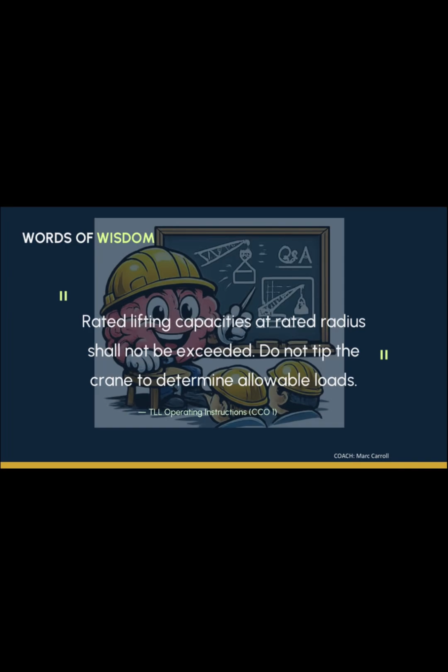Dynamic swinging. Control your load. The rated capacity is strictly based on the freely suspended load, 1 degree of level, with no external horizontal forces applied. To prevent dangerous dynamic swinging or pendulum action during rotation or transit, a tag line or a straight line must be utilized. Control your load. Start slow, end slow. Prevent dynamic loading and dynamic unloading if something catastrophic happens.